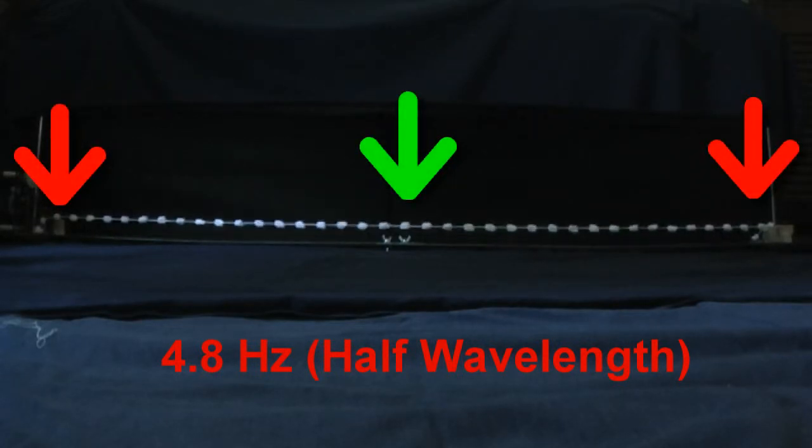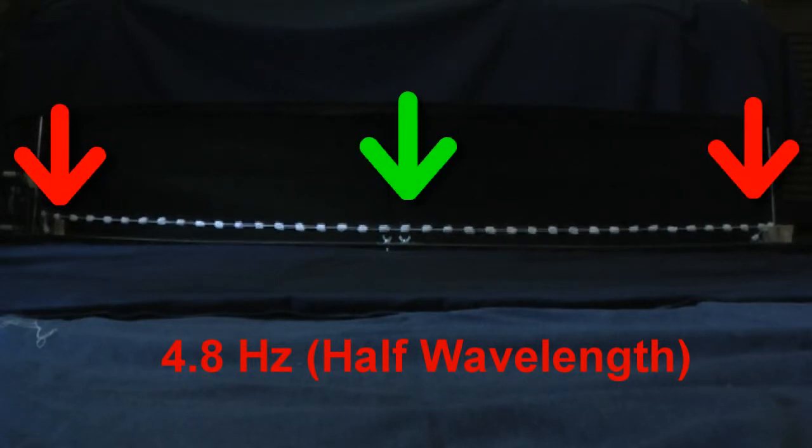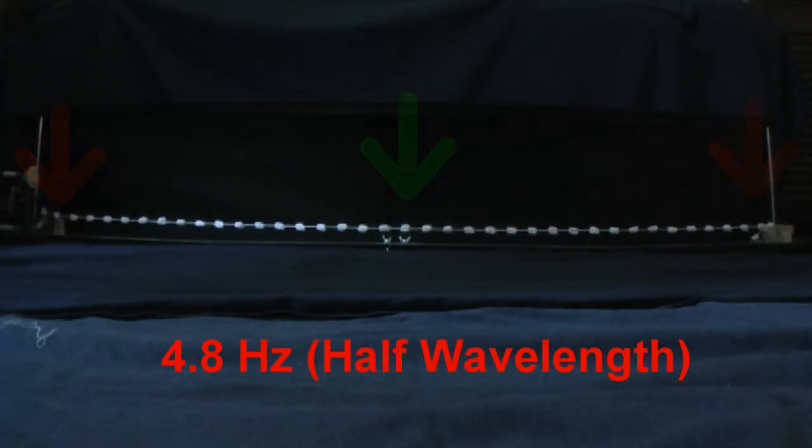A wave traveling from the center and reflecting from the right travels 180 degrees. In that same time, the wave sourced by the generator on the left travels 180 degrees. When the reflection from the right meets with the generated wave from the left, the two signals are 360 degrees apart. They're in phase and add constructively.